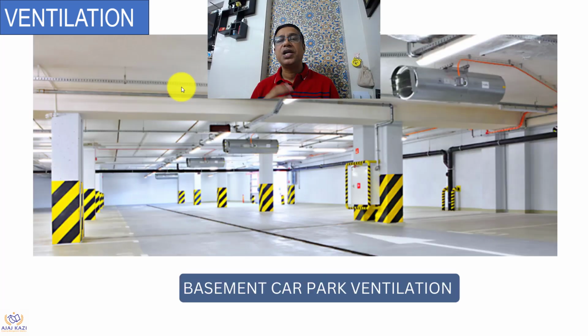Next is car park. And again, this is related to the cars being parked. When they come in, they have exhaust which has CO, right? So we have to remove the CO, which is the exhaust when the car comes in. That's one area of exhaust or ventilation. For that, we need to have fresh air and exhaust, and if the car park is huge, you need to displace that air from the fresh side to the exhaust point, and for that we generally do ducting.